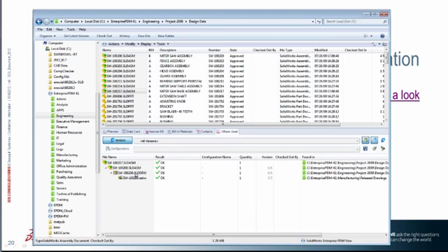When this drawing got approved, we have tasks that can automatically create eDrawings or PDFs or whatever your output file might be, and create that output file, maybe put it in a manufacturing or a vendor folder, and you can also associate the two. So if I looked at this eDrawing wherever that lives, you can see it's in manufacturing release drawings. You would see the relationship to the drawing.